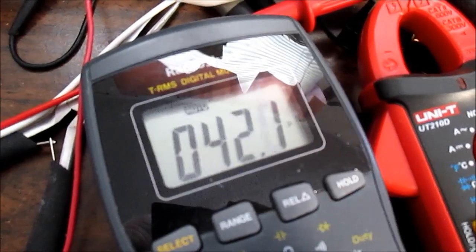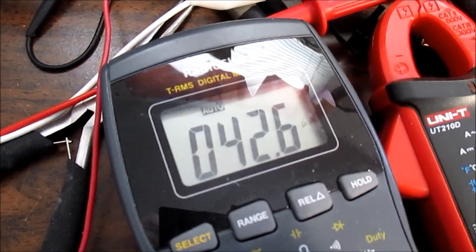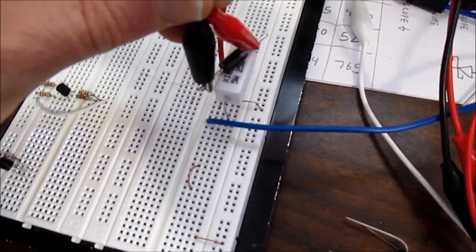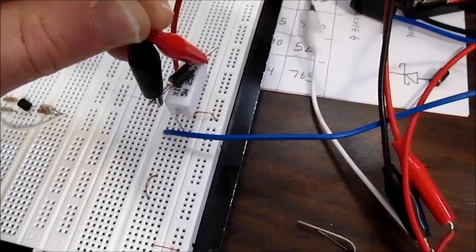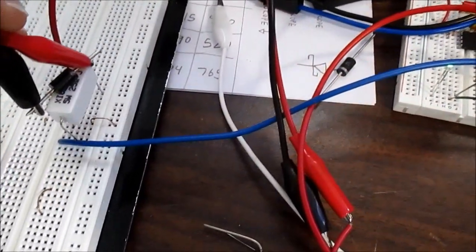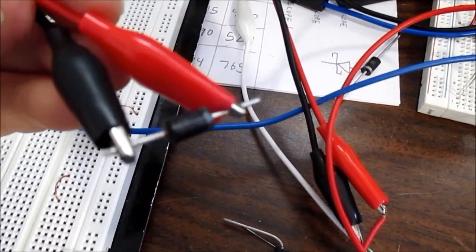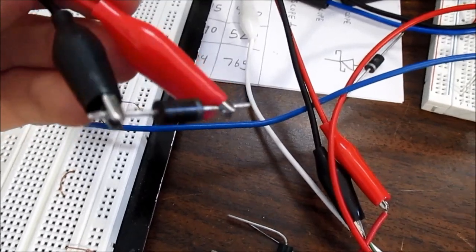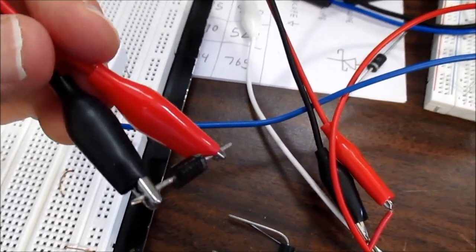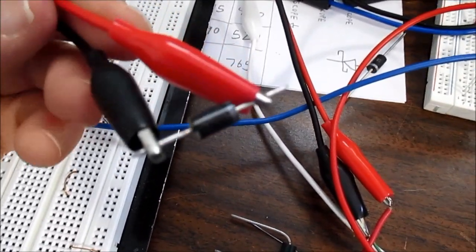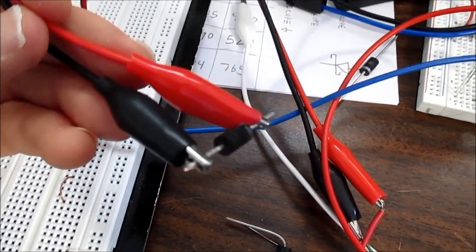But in some situations where the diode can get really hot, the reverse conduction can become significant and thermally run away, actually. But the diode would have to get really hot to do that. It'd be a poor thermal design for that to happen.